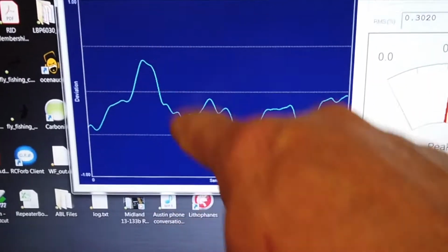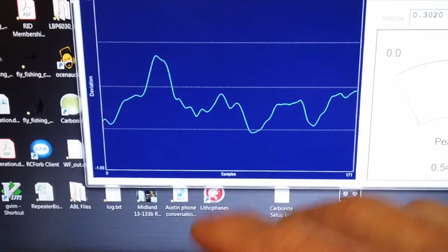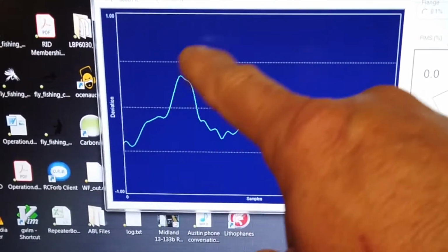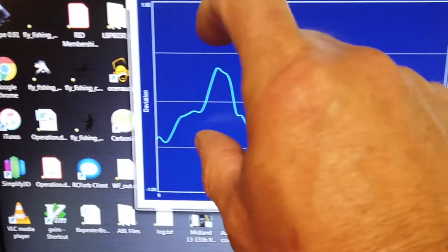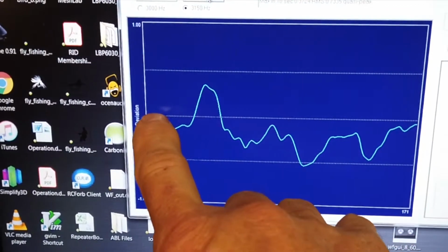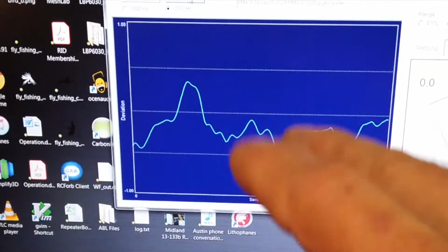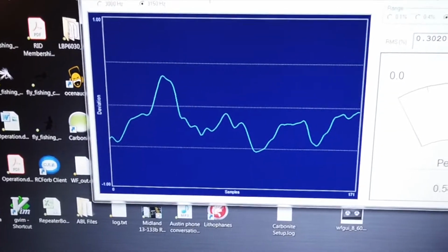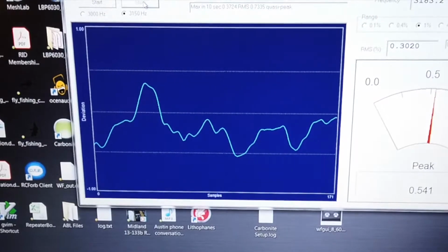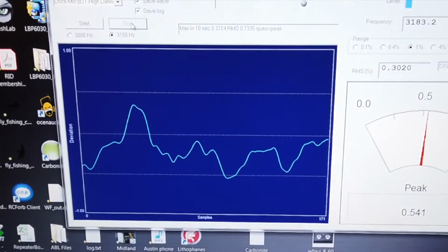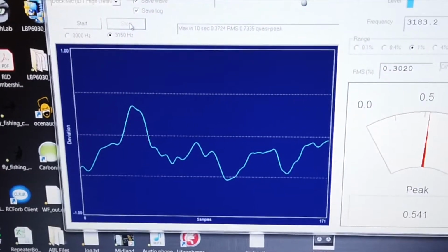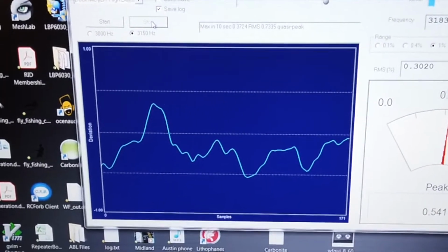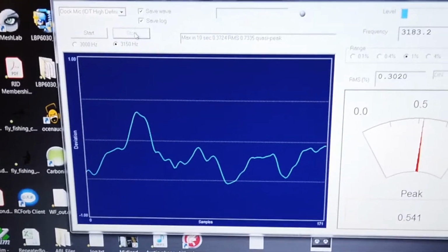Still, you can still hear the tone on the recording, and this video recording, and you can see the deviation on the screen here. Remember that zero deviation means that there's no wow or flutter. And in this case, we know there is some wow and flutter. And keep in mind, this is a recording of an imperfect tape recorder to start with. So we've introduced some wow and flutter into the test, and we would need to factor that in.